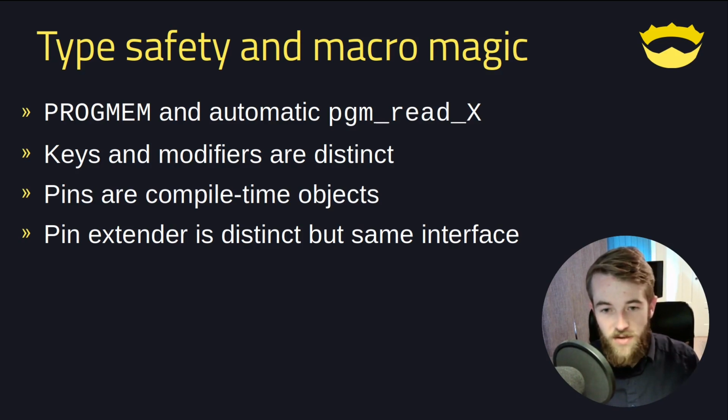Pin extender is also distinct from the internal pins, but it's the same interface. So using the pin extender is just dropping in a couple of lines to enable it, turn it on, tell it which I2C address it has, and then you can do the same, like P0 is pin extender pin 0. And we can use that in exactly the same way as we would use internal pins.